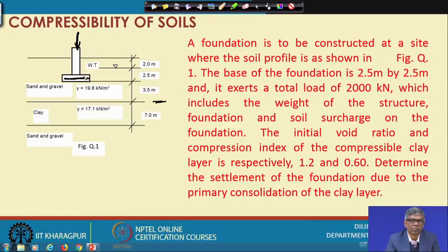How much will this foundation settle? If the building load is applied through this, then after some time this foundation will go down to some depth. That amount is the total consolidation settlement you have to find out. This settlement again will have two components, which I have mentioned.